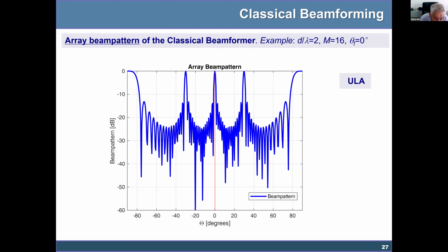So you don't go beyond that because of the grating lobes. So we choose the maximum value. Why the maximum? Because if d is the maximum possible, you have the maximum aperture, and the maximum aperture means the best possible resolution, so the narrower main lobe, but taking into account the Nyquist criterion, and the maximum of d over lambda is 0.5.